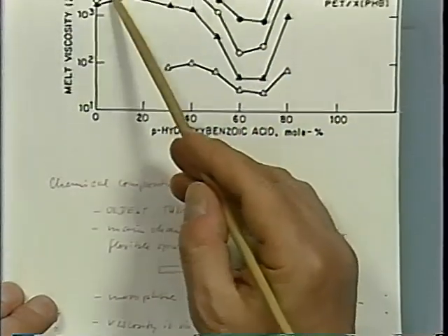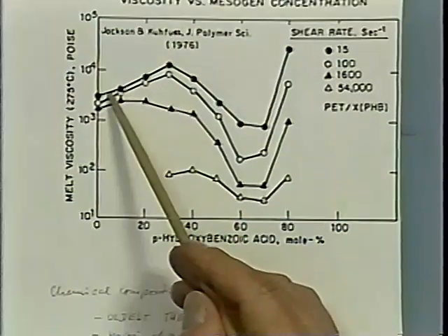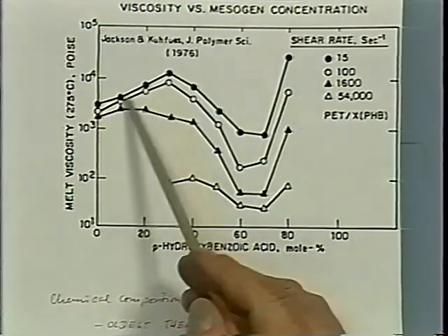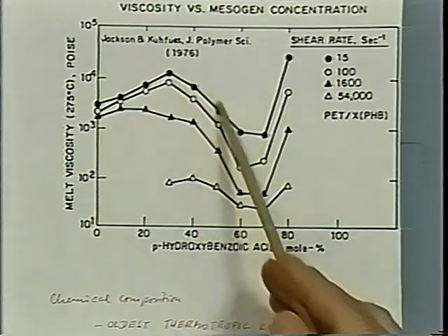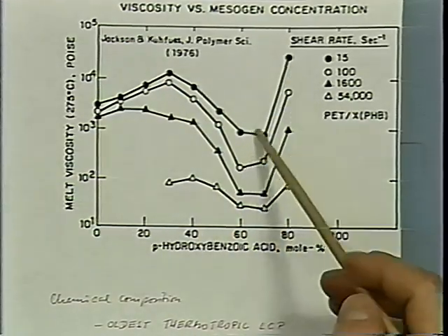First, when adding those liquid crystal elements, those mesogens in the backbone, the motion of the chain is hindered, but then in the nematic phase, motion is increased. And then again, when it gets very stiff, you cannot melt it anymore, and it doesn't move. You would have to use solvents to lower the viscosity. This example is a thermotropic liquid crystal. There are other systems where the chain is so stiff that we are not able to melt the system at reasonable temperatures. We have to add solvent to mobilize the molecules.